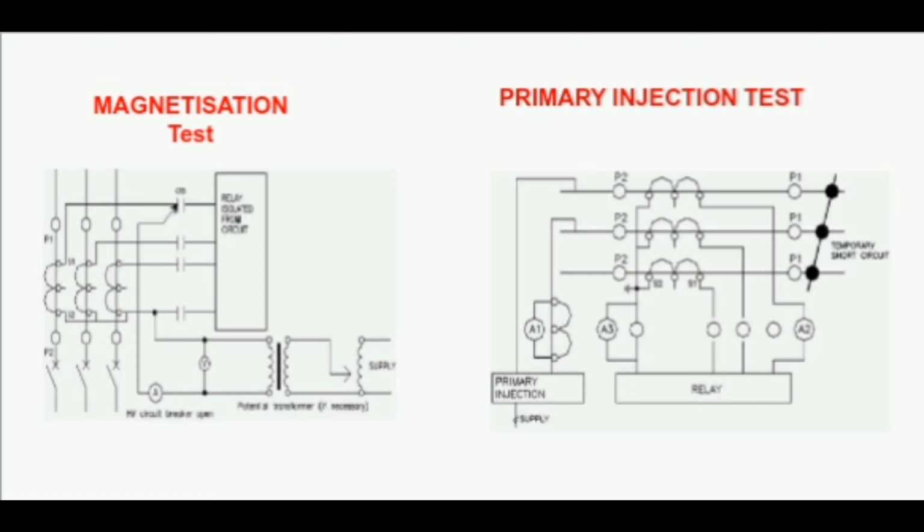You can see the core identification when one CT has several cores used for different purposes. The cores can be identified during the primary injection test by shorting the core CT terminal. Check that there is no current, except in the relevant load. The same can be verified for other cores. Inject 25% of rated primary current between phase to phase with all burden connected. Measure secondary current at all points of the CT circuits. It shall be done for the other phases as well. So now you know how to inject primary.